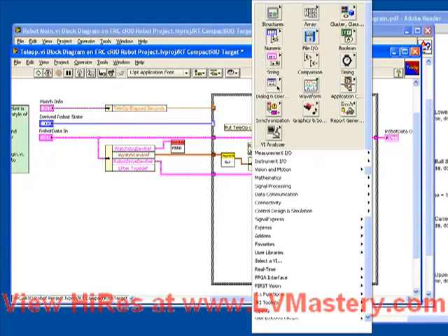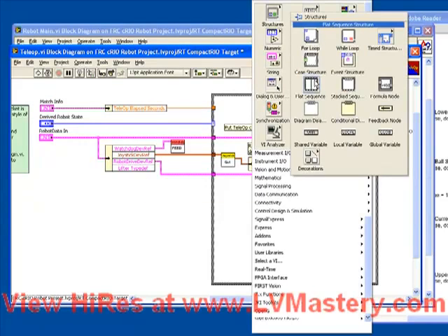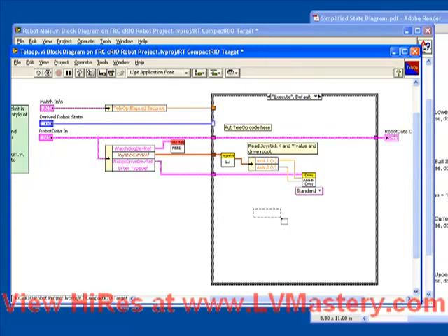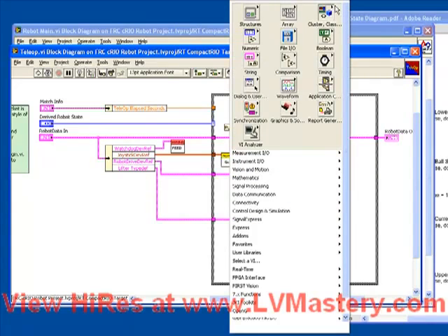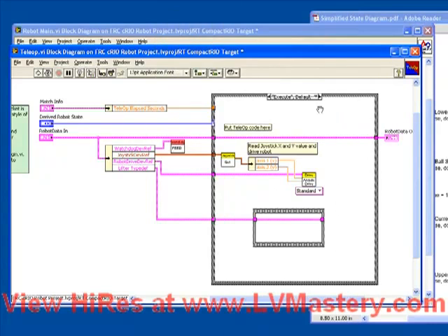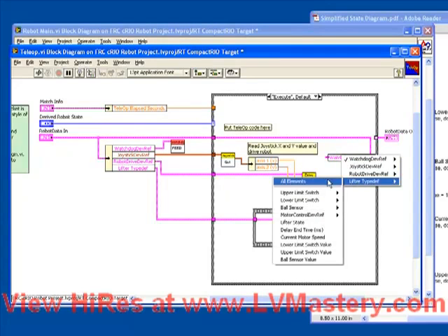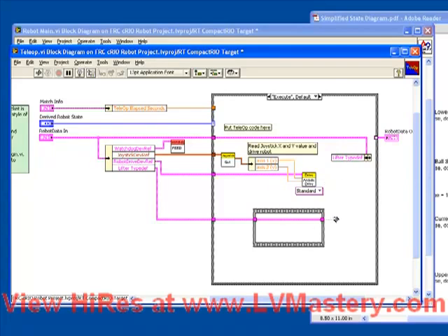So remember the shortcut to creating a sub-VI like that. We just create a temporary sequence. We wire the inputs that we want. We use a bundle by name to have a place to wire it out again. And then we make a sub-VI from this.